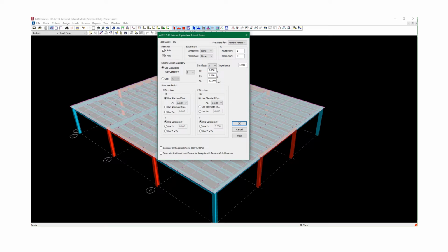I'll go back to that dialog box in a minute, but when you use that selection for your general criteria, the direct analysis method, you're reducing, by default, your EI values by 20% and using a value of 0.8. And it's basically accounting for residual stress and the spread of inelastic behavior, if you will, and elasticity of the cross section.